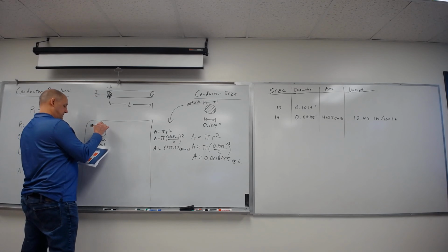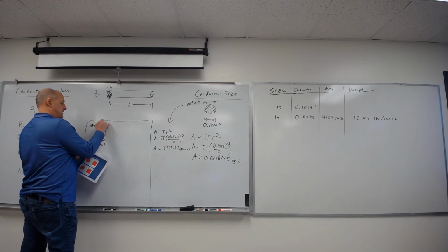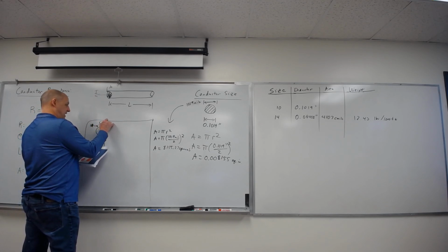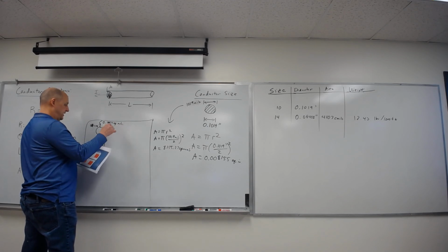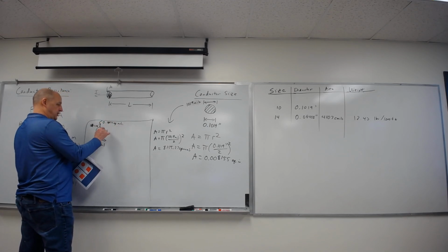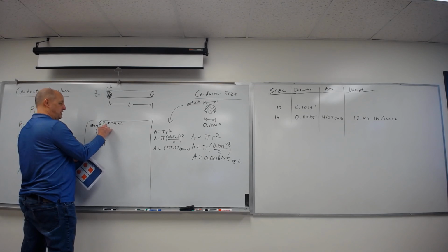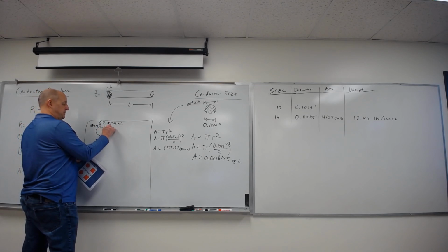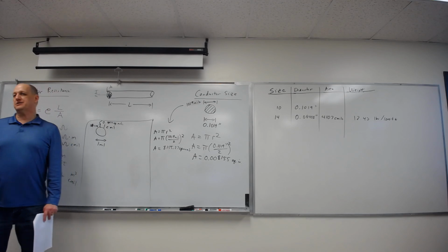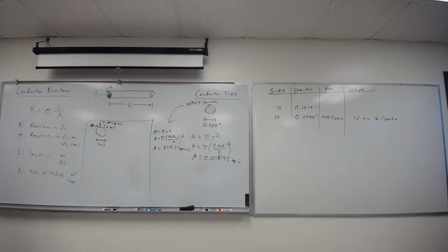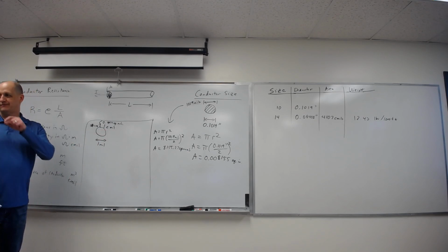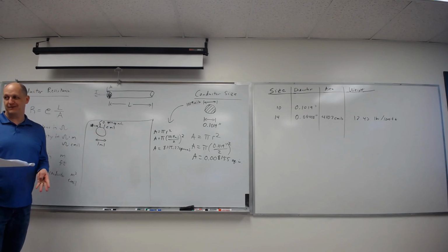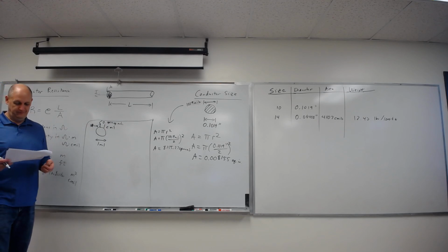so I have two choices. I can write it as 0.7854 square mils. Do that calculation just like that. Or I can look and say, 1 mil across, I'm just going to call this 1 rather than square mils, C mil. That's what a C mil is. It's a circular mil. So conveniently, I can just go, it has a diameter of 1, it's 1 circular mil area. It also stays consistent, my units everywhere. And that's what I put in my table.